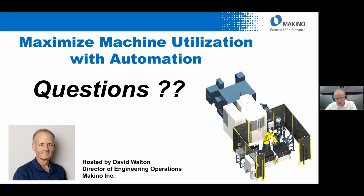Another question has to do with the implementation of cobots. Is there any difference between using a standard robot versus a collaborative robot? One of the biggest things that we see as far as that integration, obviously your robot interface is pretty much the same, but it has to do with now protecting some of the operations that are occurring with the machine, such as the access doors opening and closing, and maybe the clamping of the fixture.